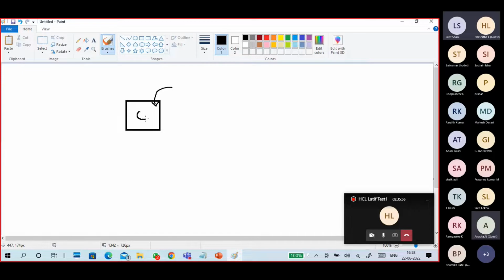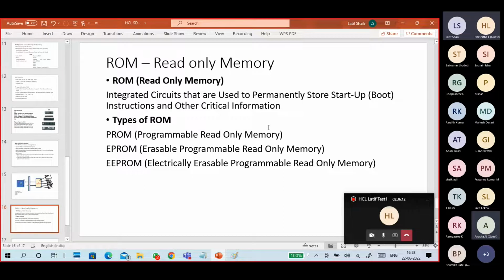In earlier days, we had a type of ROM chip that comes with a small glass piece on it. So you send a program inside using UV rays. UV rays, okay, ultraviolet rays. They will send it inside to program it. It's hard programming again. In later days, erasable programming came, meaning there is an empty chip. You can program it. If you see its program goes wrong, or you no longer require a program inside your ROM chip, you can erase it. You can rewrite the program in the ROM chip, that is EPROM, meaning we can rewrite it.